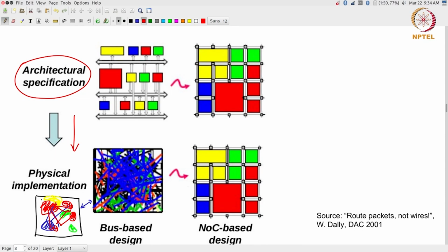Why does this happen? Because the synthesis tools are taking the large number of gates that you have and trying to optimize them. They are trying to optimize the placement, they are trying to optimize the routing, they want to minimize the wasted area as well as the length of the wires. So they say, look, anyway you are not going to go in there and fiddle around with these gates, let the tool decide the optimum placement so that your performance is best. This is what you end up with.